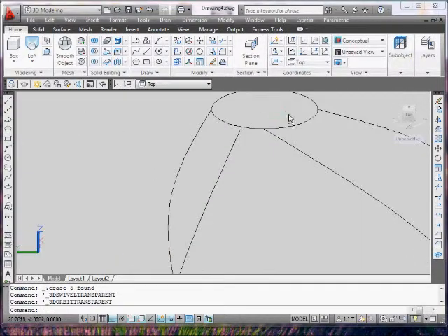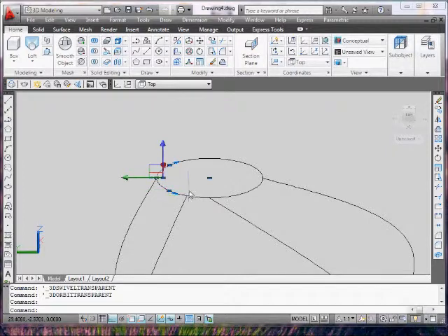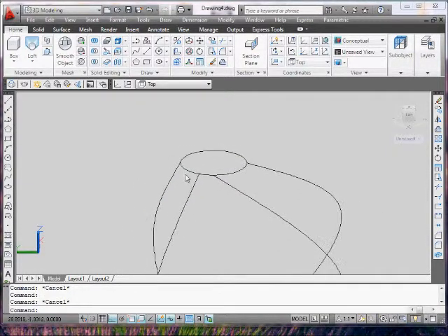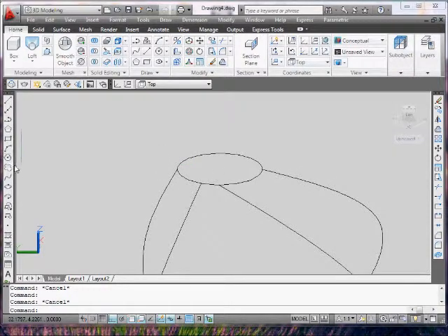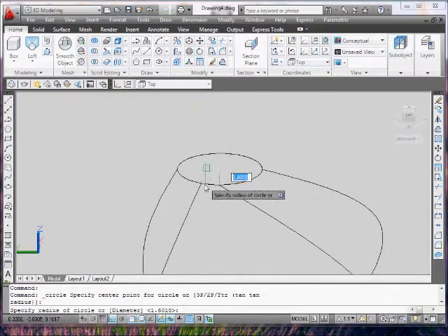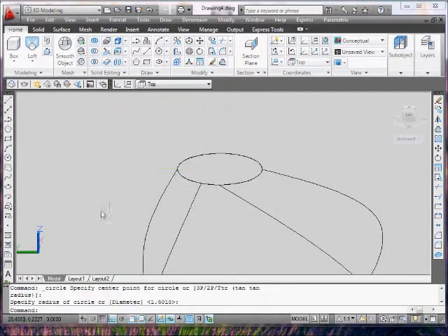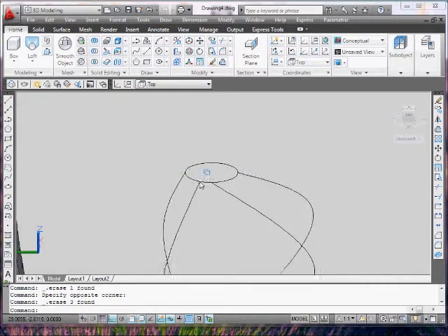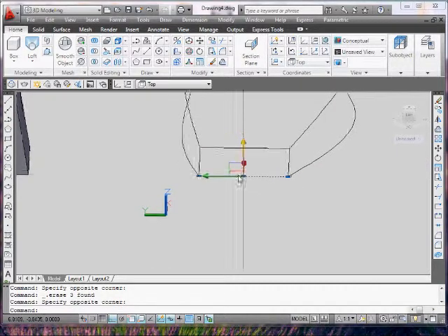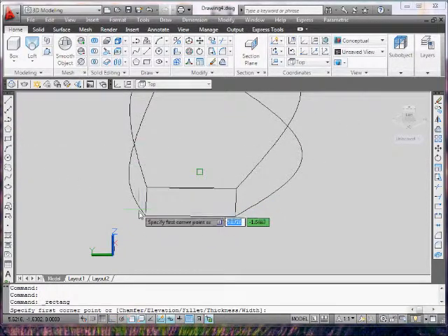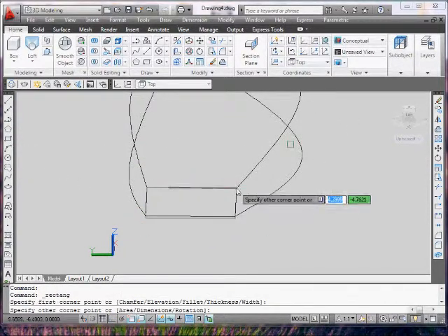But you know what the problem might have been? The circle is exploded, so it's no longer an actual complete circle. It's actually segmented. So I'm going to redraw a circle on top of it, and I'm going to delete those segments that I'm not using. There we go. The square is not fine too, so I'm going to do the same thing with the square.